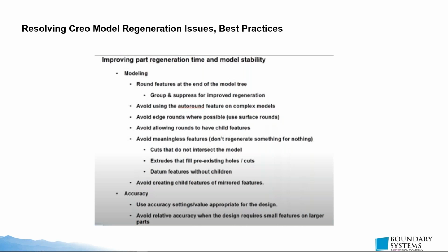And datum features without children, why have them in there? Datum features don't take a lot to regenerate, but it does expand the length of your model tree. So you have features in there that you don't need anymore. So get rid of them if you don't need them.